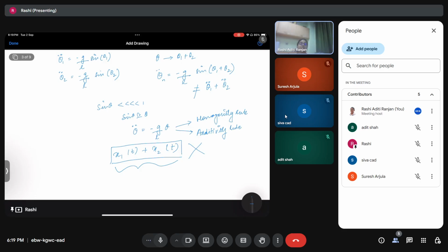So whenever you are doing any practical application of what you are learning in this course, you need to keep in mind that the range up to which we are seeing the deformation is very important. We cannot ignore the limits that the system is going to have, right? Otherwise, you are going to find the solution through the superposition rule, and when you do any kind of practical testing, or even if you design a machine, and you don't focus upon the linear zone, then it can lead to catastrophic failure of the system as well.